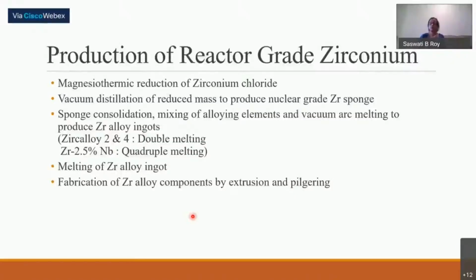If we see the material of construction in this whole process, you will be surprised, because chloride is very corrosive. So for that, chloride-resistant cans have to be employed. And then for other materials where heat sensitivity is required, different grades of stainless steel will be required.